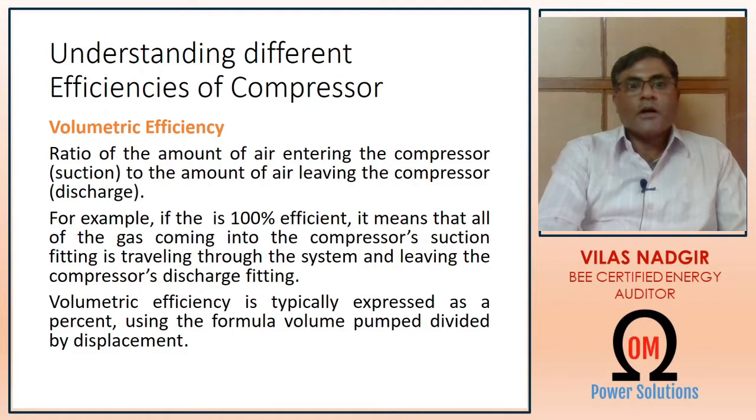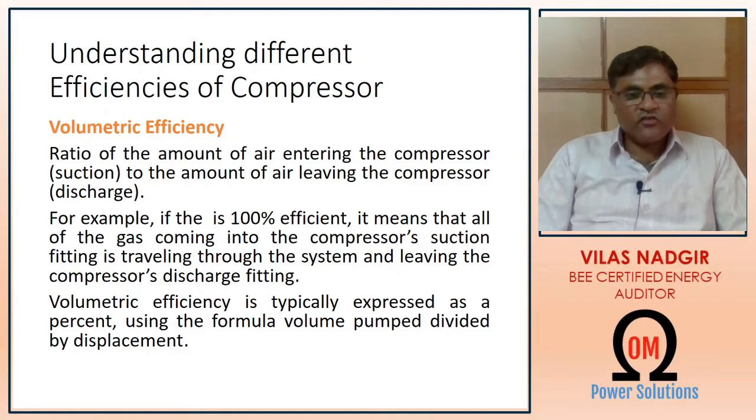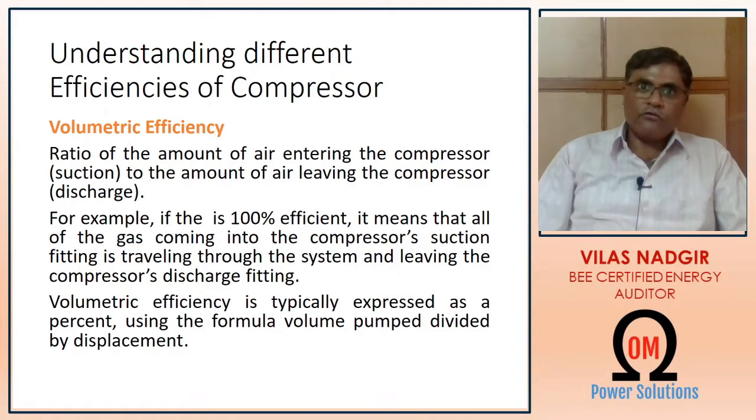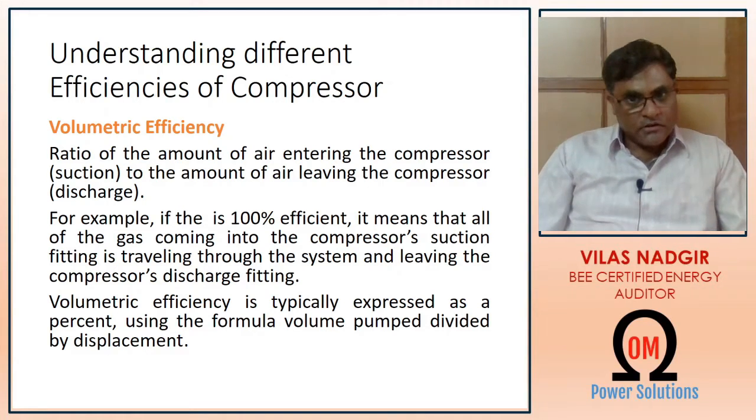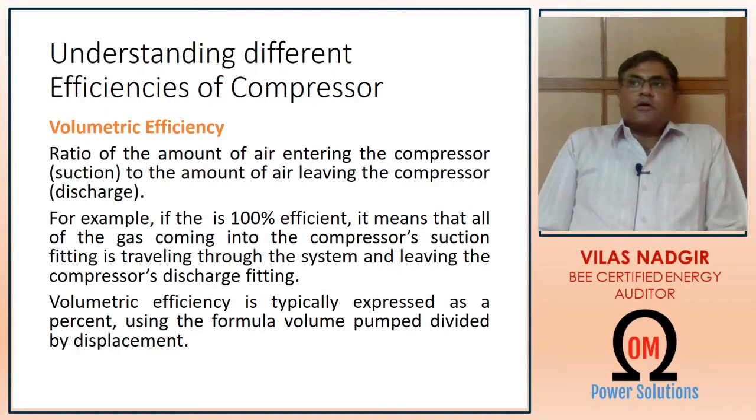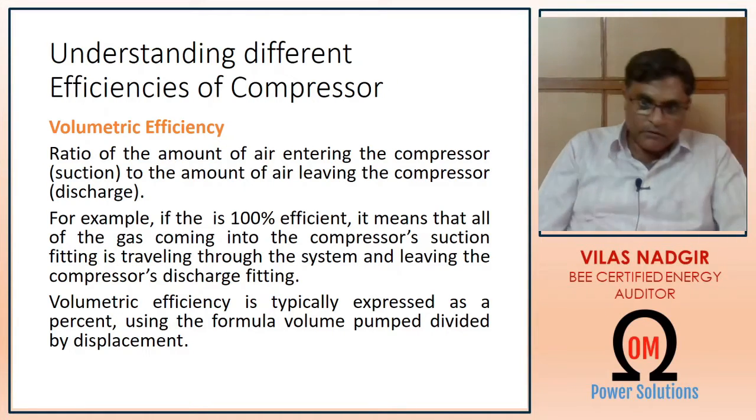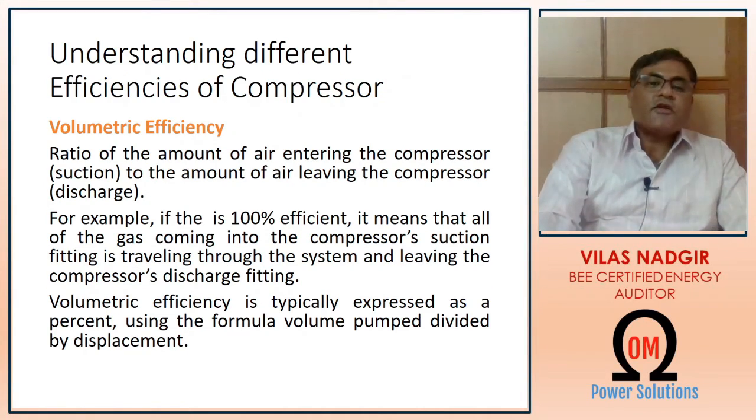So this is the term which we have to understand, that is the volumetric efficiency. In a vague definition, I can simply tell you that it is output volume divided by input volume. If the output volume is equal to input volume in any compressor, then it is 100% efficient. But in practice, the output volume of air in any compressor will not be equal to the input volume. There are a lot of parameters associated with this. Output volume will always be lesser than input volume because of heat, friction and other types of losses. That is volumetric efficiency.